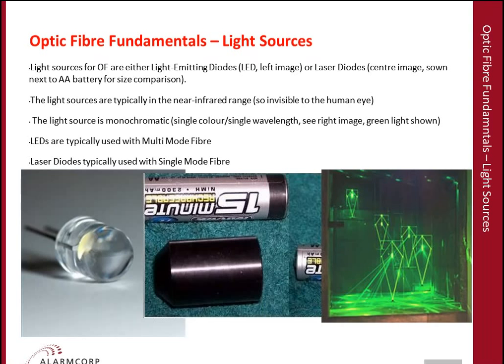LED light sources are typically used with multi-mode fiber, whereas laser diodes are typically used with single-mode fiber. And we will explore that in the coming slides as to what the difference between those two is and why you would use a particular light source with a particular type of fiber.